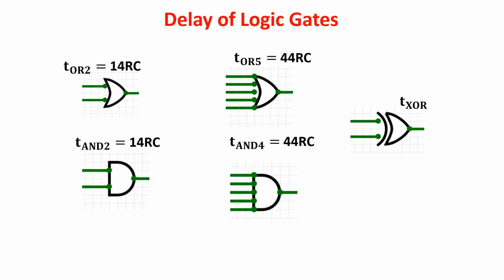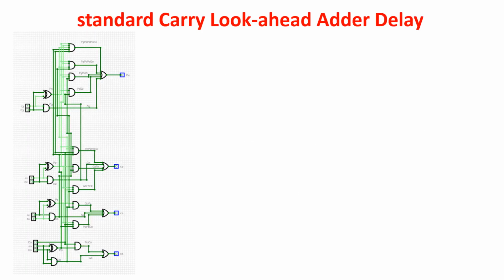Actually, the PMOS resistance is different from that of the NMOS. We could make them equal by making the PMOS larger, but we would have an impact on the capacitance shown by the PMOS. Moreover, the capacitances are not all equal, but we want just to give an idea and keep it simple.